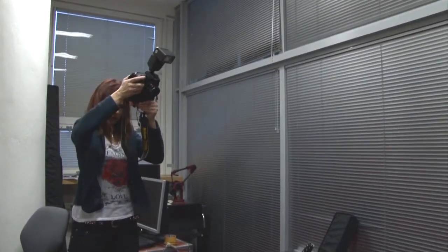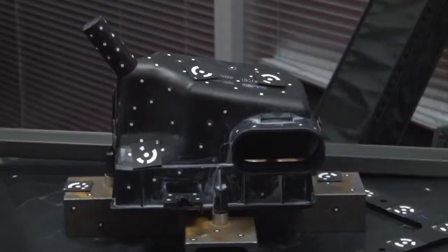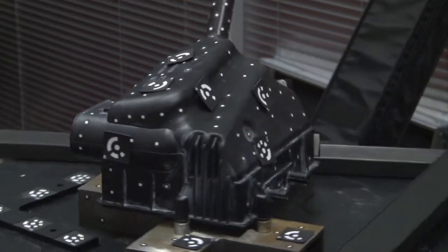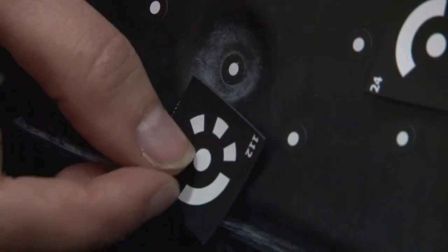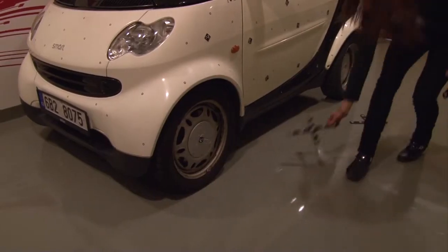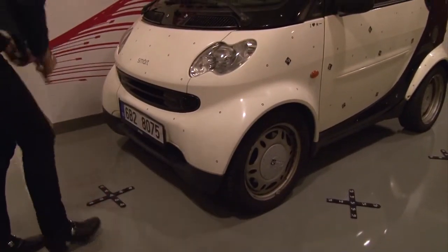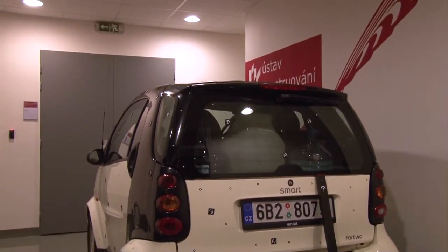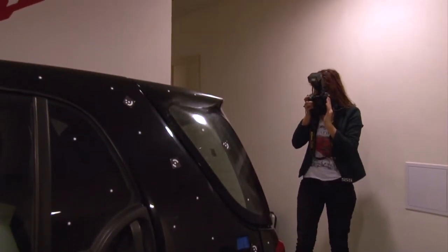Photogrammetry based measurements are used to digitalize the position of reference points applied on the surface of the object. The obtained coordinates of these points are then used to reconstruct the shape of the object or to analyze the object's dimensions. Another use for photogrammetry is to measure deformations. We provide the measurements using the TRITOP system.